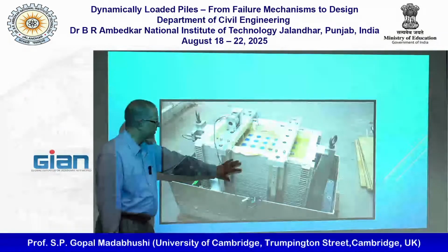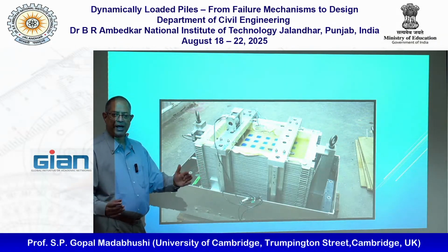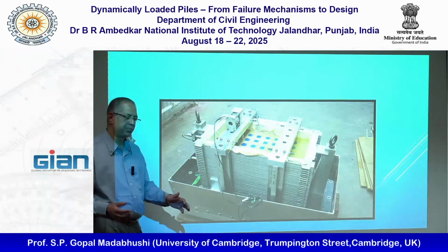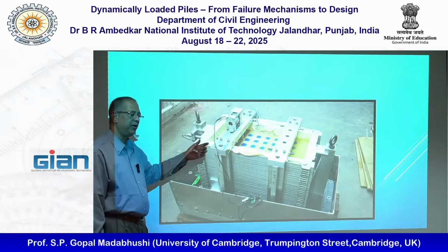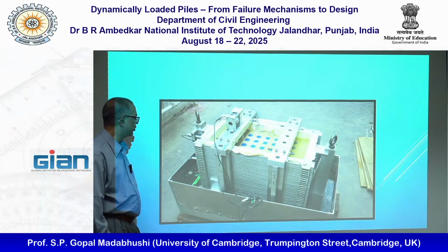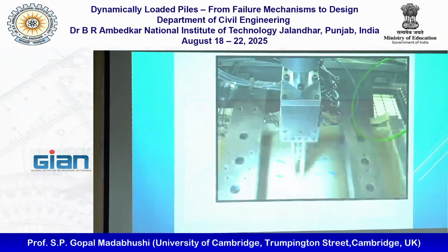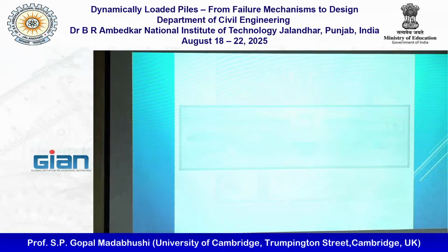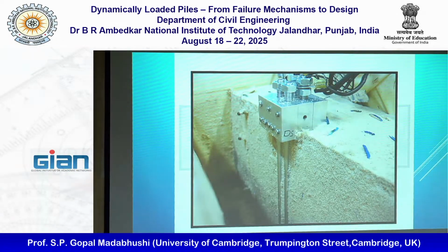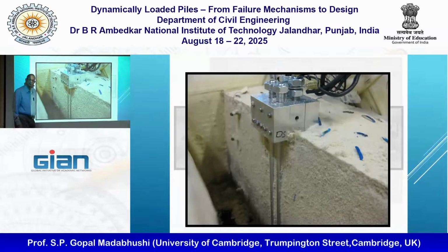Also, we make the model horizontally and we put it on a wedge, either a 3-degree slope or a 6-degree slope, and you mount them on wedges. This is what we do for other tests as well, which I'm going to talk about tomorrow, Knappett's test. And then you drive the pile. This is obviously the 2D spacing pile. And then you put it on the centrifuge and you do the test. And then post-test you can also excavate and see where this ended up.